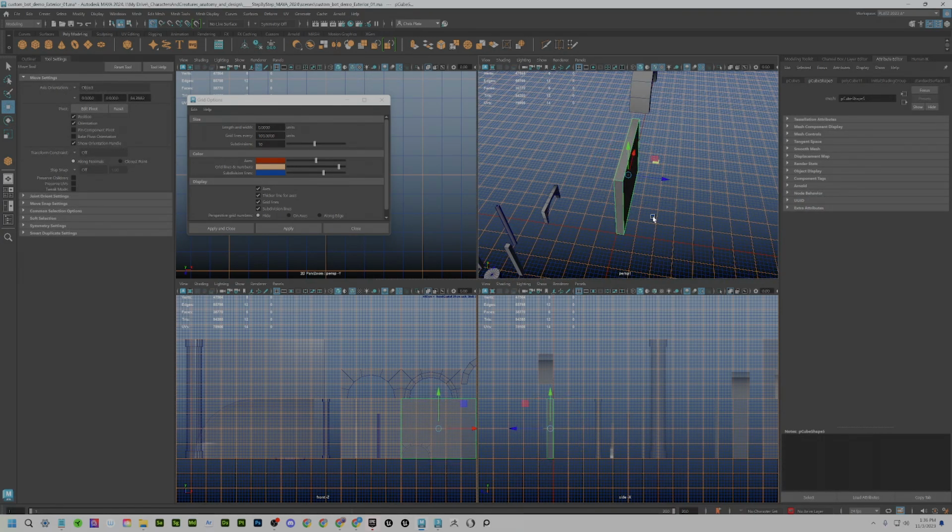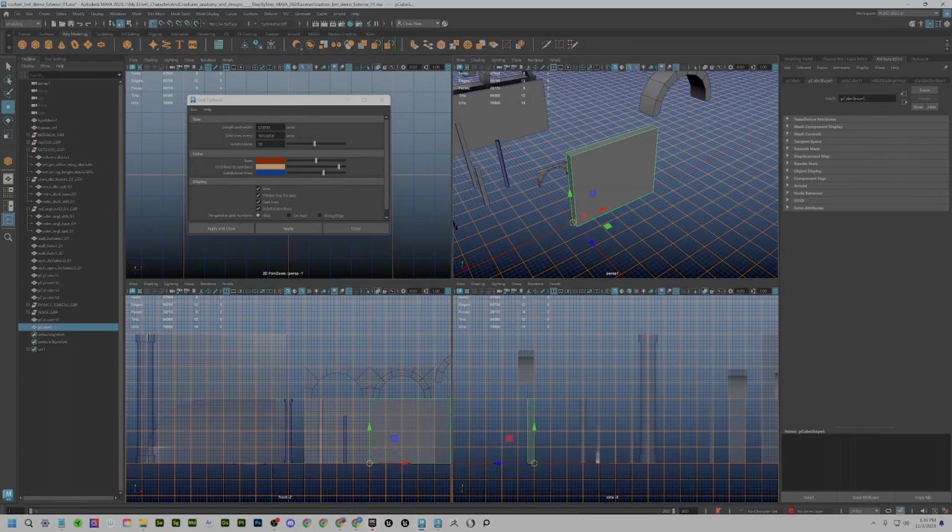And then same thing with the interior architecture. We're going to hold down D and snap that to the inside corner, and that becomes my exterior wall piece. And I'm naming them as I go. So for this one, I'll go EXT underscore WALL underscore, and then you do the width and then the height and then the depth is last. So the width on this is going to be 4 meters by 4 meters high by 0.2 meters, which is 20 centimeters. And that should be the measurement I have here.